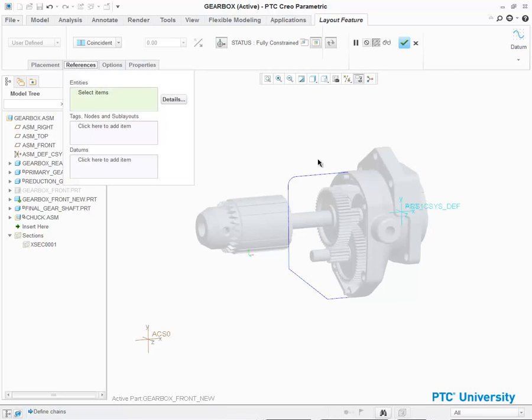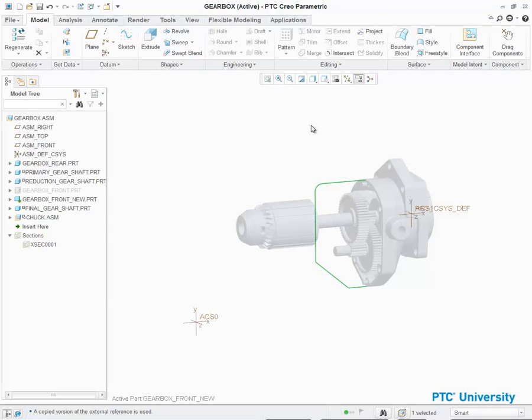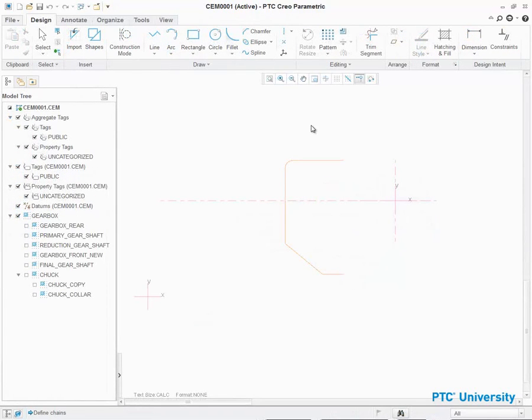We will now specify what layout components are to be referenced in the assembly. The layout is now a component in the assembly. You could now reference any of these curves to create geometry using standard tools such as Copy Geometry. Finally, let's window back to the layout. From here, we can change the radius of the fillet to a larger value.